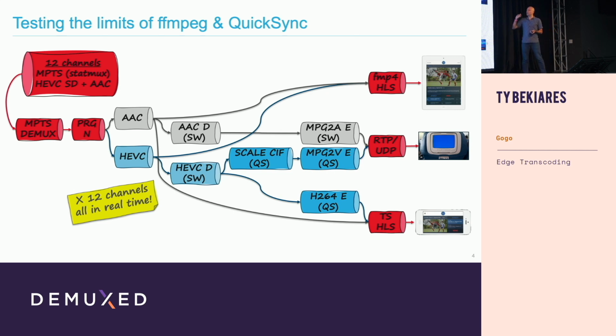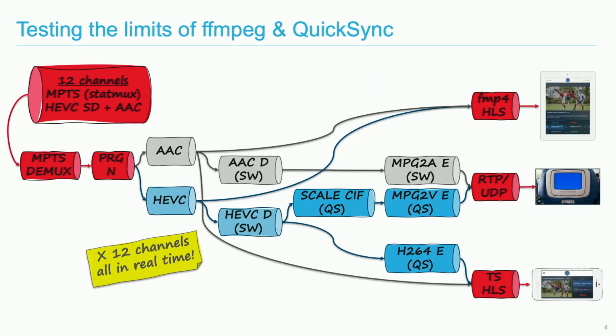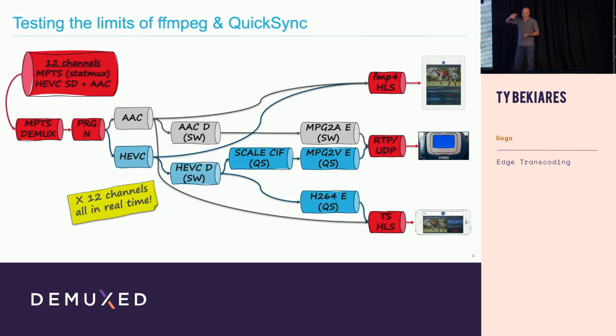One thing that wasn't inherently obvious to us is that the timing of those systems is spot on. All the timing is essentially driven by the ground. You probably have a rubidium oscillator somewhere in the system. And if you looked at the output of an IRD going to IP, it was perfectly conformant to the TS buffer model.